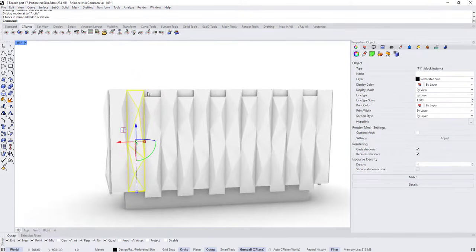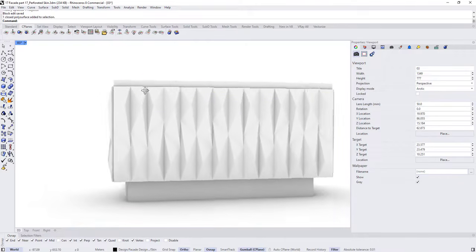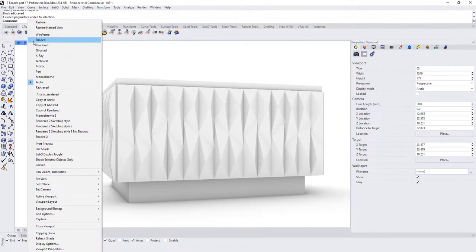You know what? Let's move this down back again. I don't think we need this. So double click, hold Control Shift, select this one, and let's move it down with a value of 1 meter. And we can just keep the parapet something like this. It doesn't look bad, by the way.